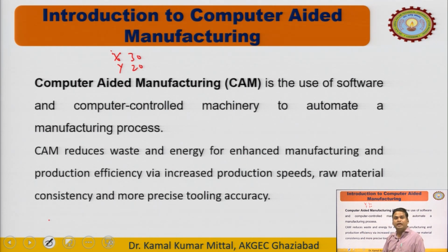Now, if we are using the spindle, the spindle is rotating with some revolution per minute. So, we define S words as spindle 20, whatever is the speed required. Similarly, F for feed words, that may be 10 mm per minute or whatever it may be.